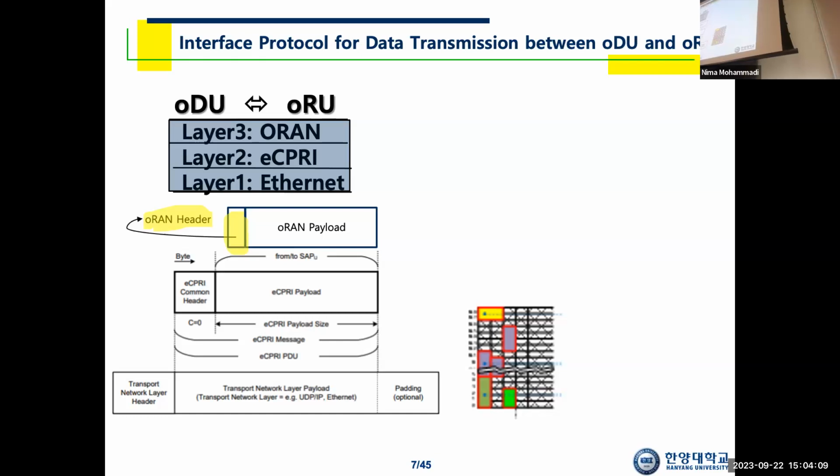Well, the ORAN header has 8 bits reserved for specifying section type. Once again, with those 8 bits, you can define 256 section types, but we have only section type 0, section type 1, 3, 5, and 6. We are using just 5 different section types. Section type 0 is used when you deal with these non-specified sections, okay? So you transmit all zeros with section type 0.